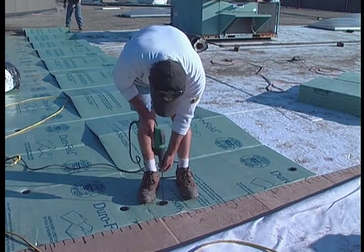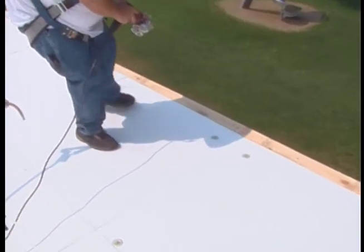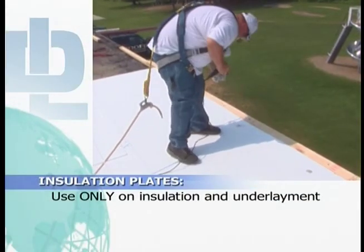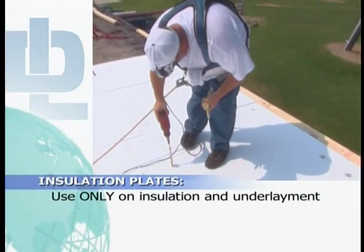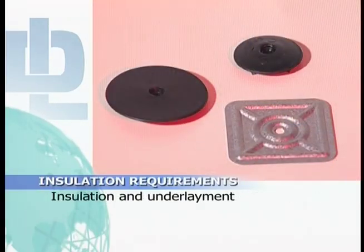Install plates so they are flush with the insulation's top surface. Don't break the facer or crush the insulation. Use insulation plates only on insulation and underlayment, not on Duro-Last roof membrane. When installing insulation boards or underlayment, use the Duro-Last 2-inch poly plate, insulation plate, or 3-inch square metal plate.